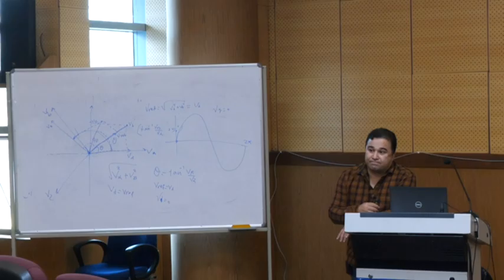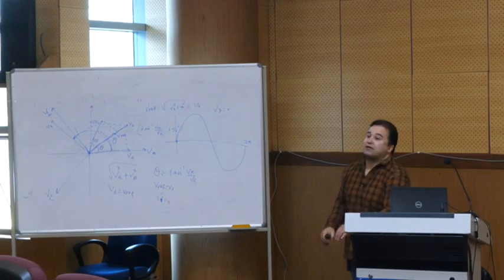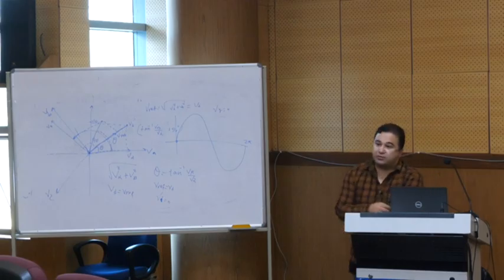For the decoupling of active power and reactive power, the reason is that you separate the impact of active power on reactive power and of reactive power on active power. Can you do that easily in Clarke transformation? In mostly MPC techniques, with Clarke transformation they don't have a coupling part. They are decoupled.